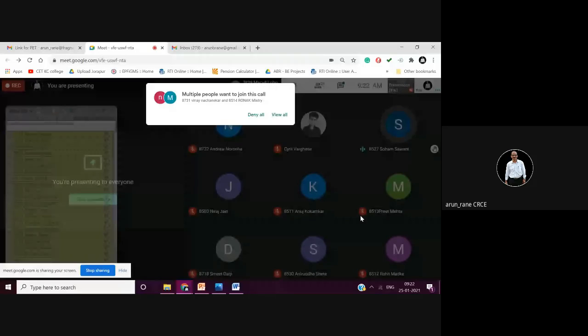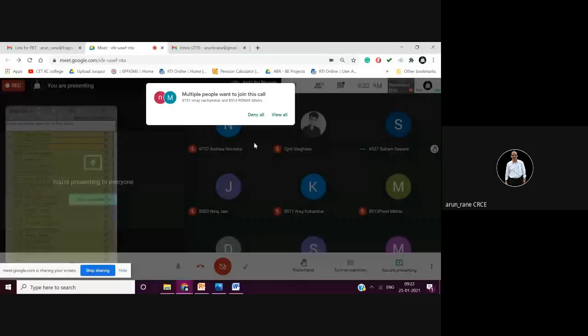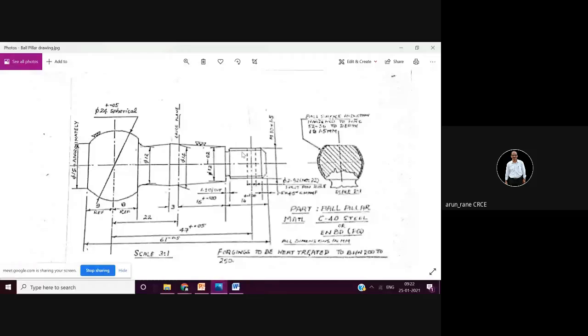So what happens in CNC lathe, there are two issues in this case. First, if you do the threading, then the drill will slip. The drill will not get a proper bite. So on the threads, the drill will slip. So you have to do drilling first and then threading. That is the first issue.